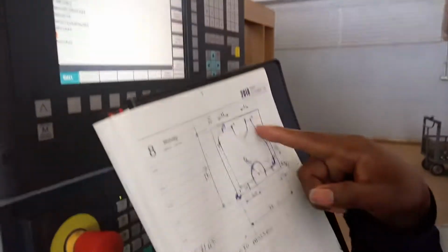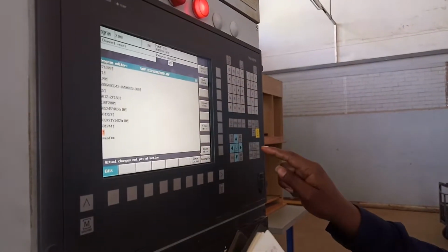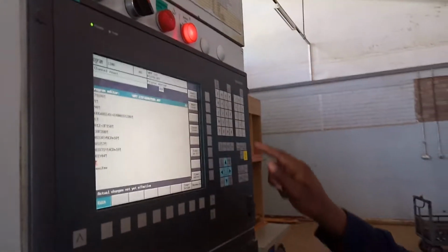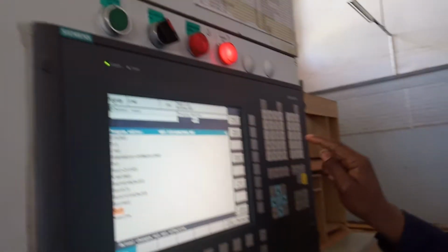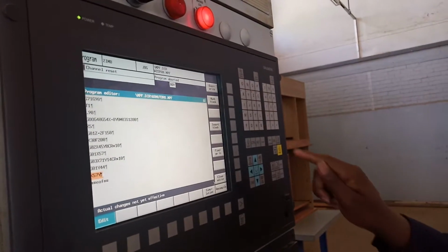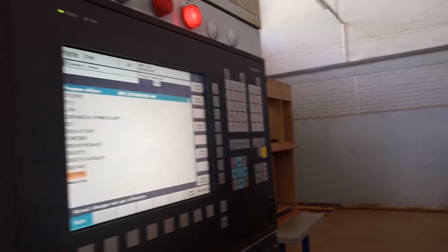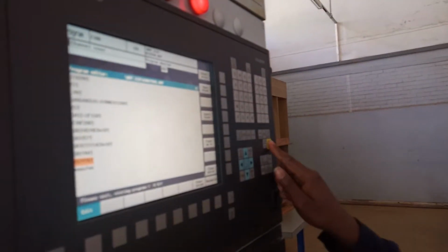Then I want to cut a taper. I want to cut this taper here. Okay, so I'm just gonna take my X. My X now is X57. And then in the same line with Y, Y76. That's it, right? And then I put my input.